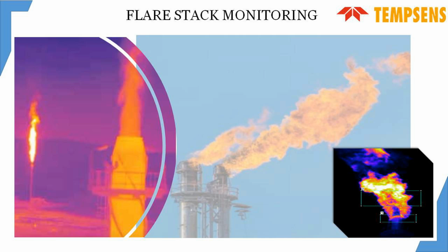These pilot burners need to be checked to see whether they are working properly or not. For that we install online thermal imaging cameras to check the current condition and temperature readings of the pilot burners: is it working fine, and is it generating a good amount of heat or not.